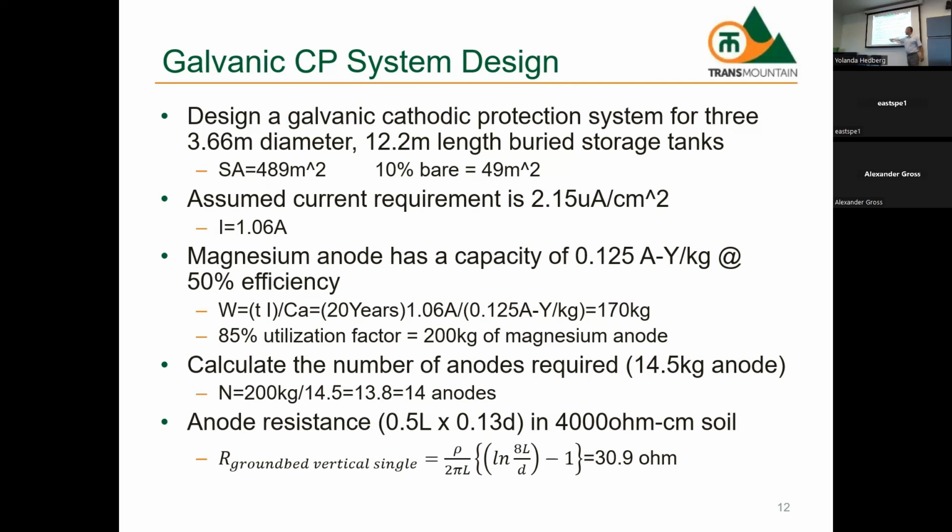So if this resistivity goes from 1,000 to 10,000, the resistance is 10 times as much, which means you're going to get a tenth of the current out of the anode using Ohm's law. You know what I mean? Yes. Clear? Thumbs up, down. Great stuff. Yes, it is great stuff.